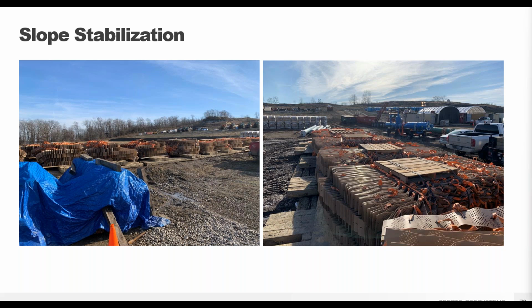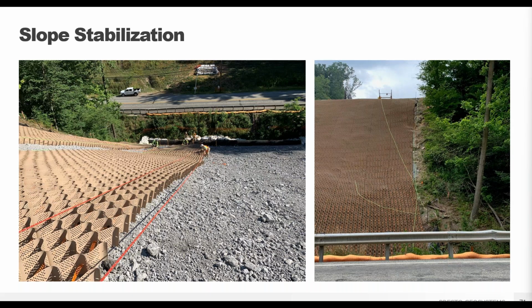The pre-assembled panels are marked for location, then taken to install, ready to hang in place on the slope. That pre-assembly means much work is done on the flats instead of slope side, much safer and more efficient for the workers.